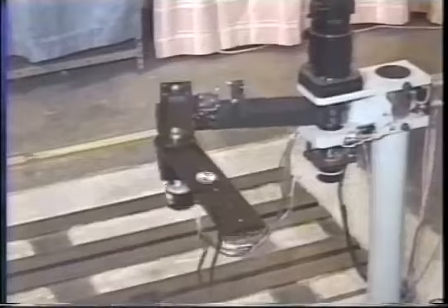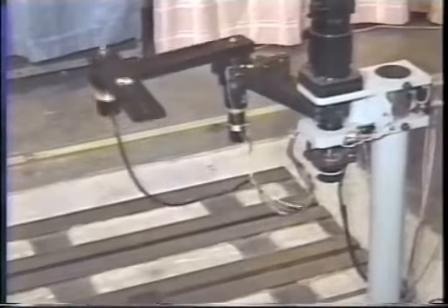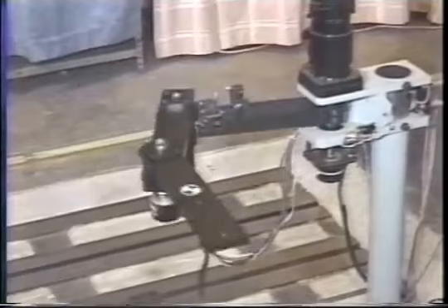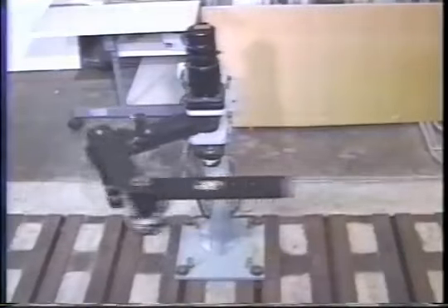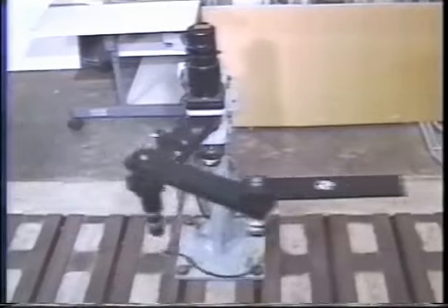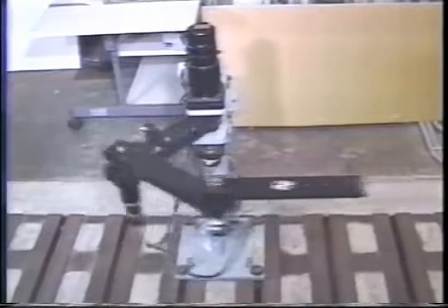The link can translate without rotation when the joint is accelerated towards the center of mass. Nonlinear feedback control stabilizes the free link to the trajectory. The motion of the center of percussion of the link is considered, and an exact linearization is applied to the system.